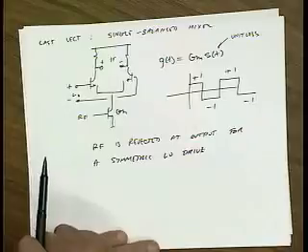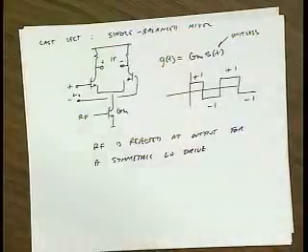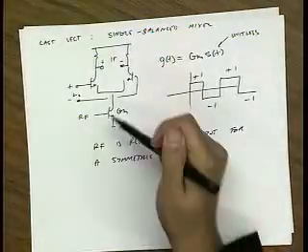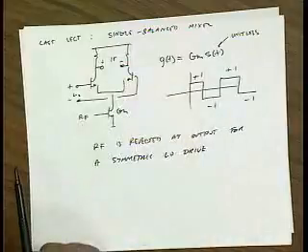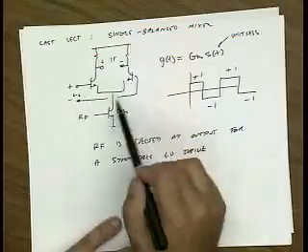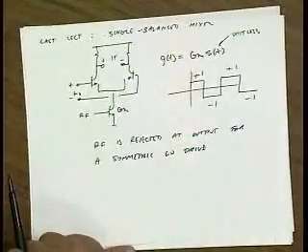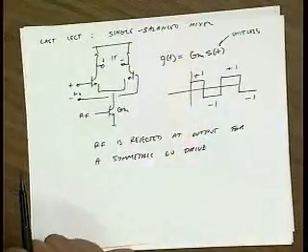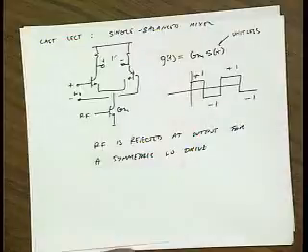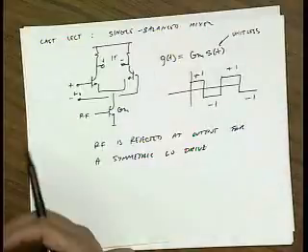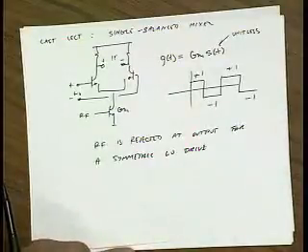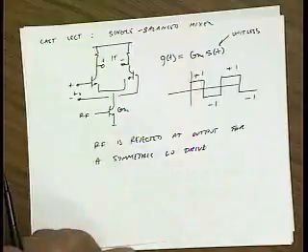Okay? Let me also just intuitively tell you something about the noise of this circuit. This is another discussion that came up in office hours today. Last time we talked about the noise in mixers in general, and we noted that one thing that makes the noise of mixers high is that the noise at all the image frequencies folds into your IF band, and so you get a lot more noise than you would from a time invariant circuit.